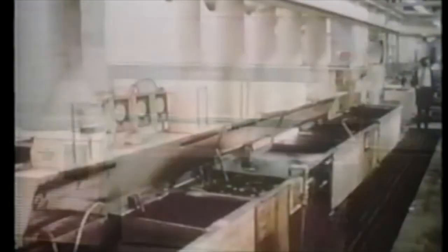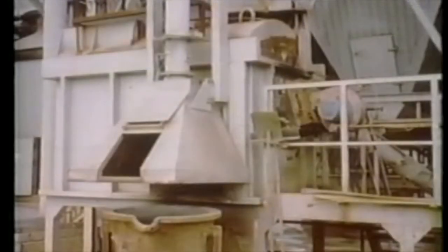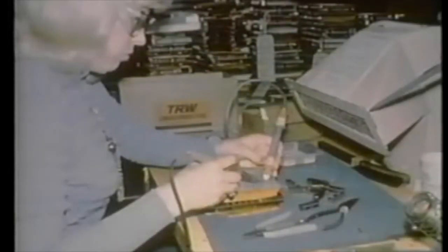There are 3 major types of hoods: those which enclose the emission source, those which capture emissions, and those which merely receive the emissions, such as a canopy hood. The most effective hood usually encloses the emission source as much as possible. When using capture and receiving hoods, place the hood as close to the source as possible. Canopy hoods should only be used on hot processes. The canopy cannot be used when workers must lean over the tank or process when contaminants are rising, since they will breathe the contaminated air.